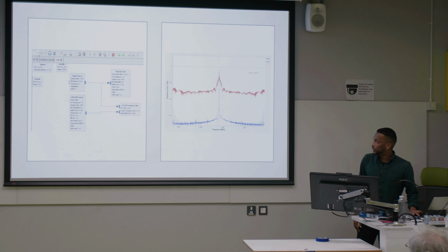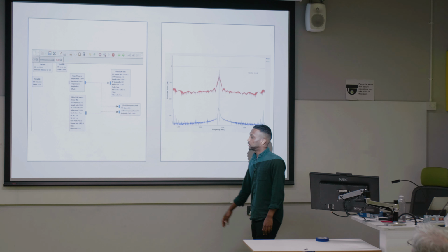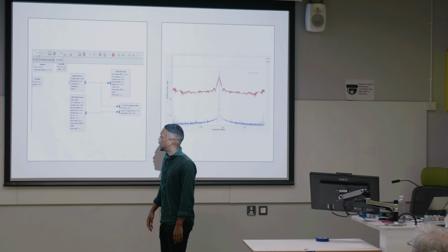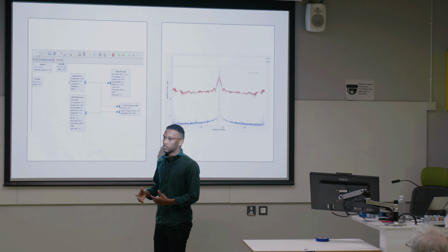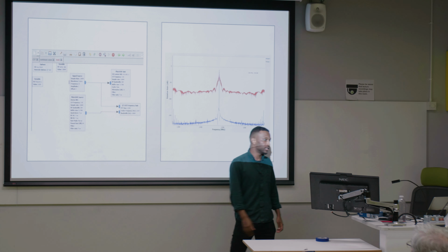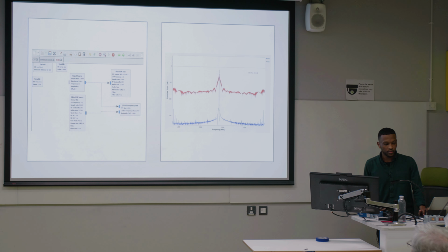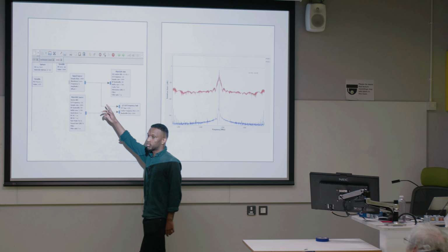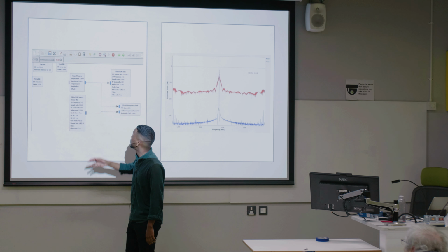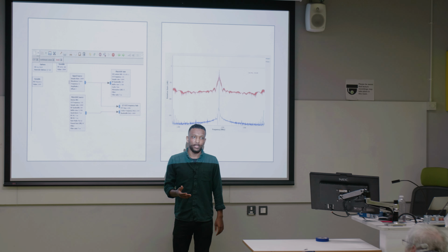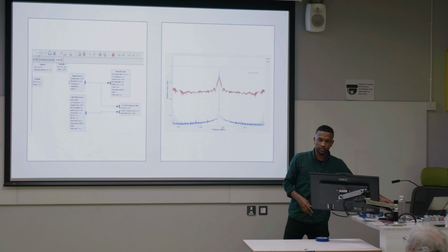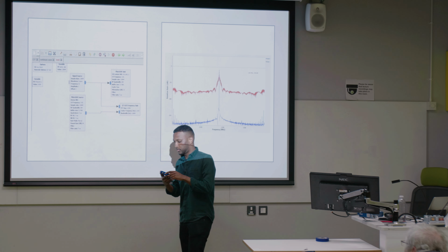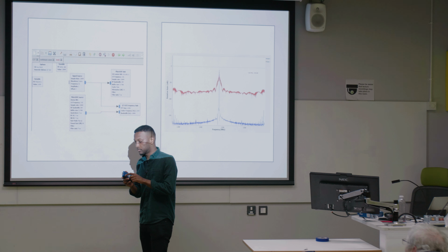And this is what GNU Radio looks like. This is what we call the flow graph of GNU Radio, and it's built of many blocks. Each block has different functionality depending on what you want to do. Firstly, to start the project, I needed to make a continuous wave signal. We have this signal source that generates our sinusoidal wave. The Pluto SDR sink is basically the transmit side of our ADALM Pluto.